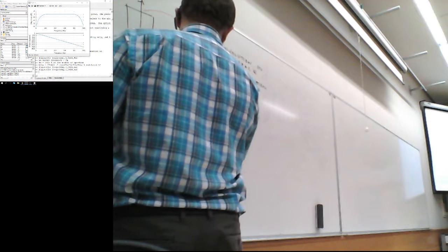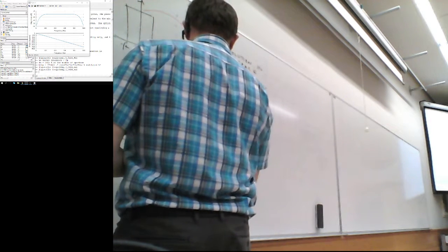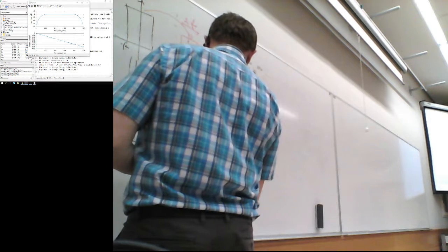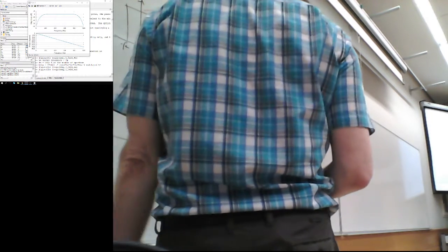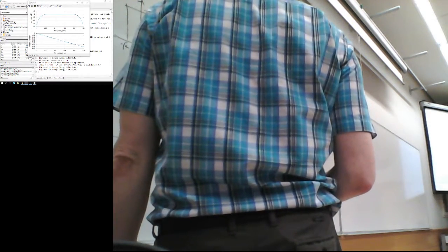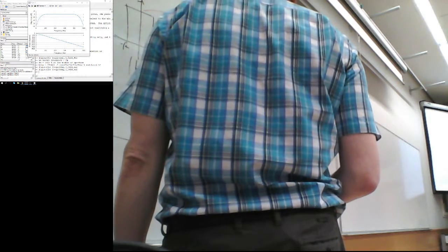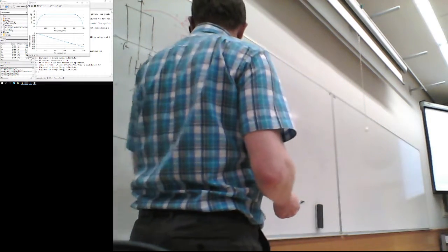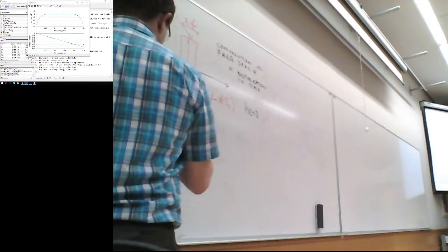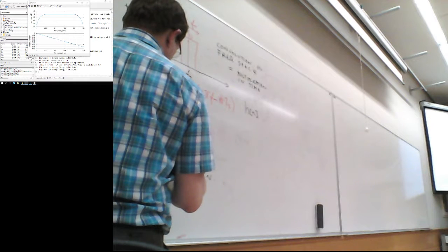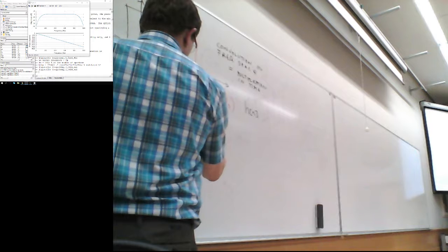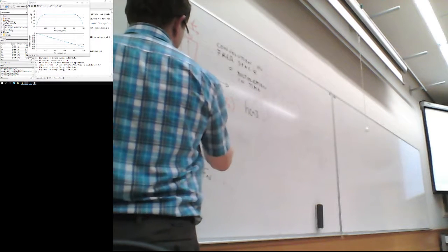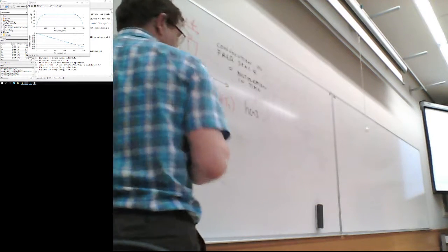If you set this modulation frequency the same as the Nyquist frequency, you actually get a filter transformation from low pass to high pass, so that the high pass filter full bandwidth is the Fc.